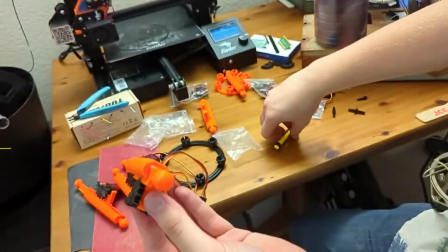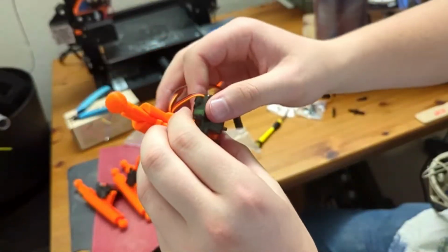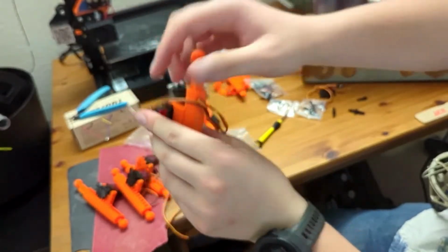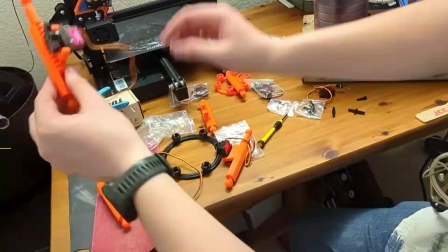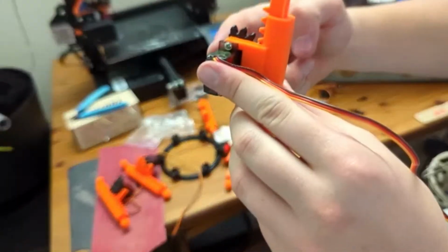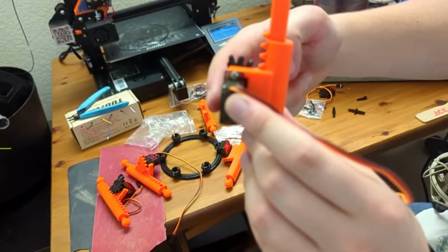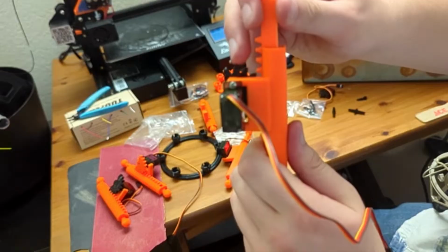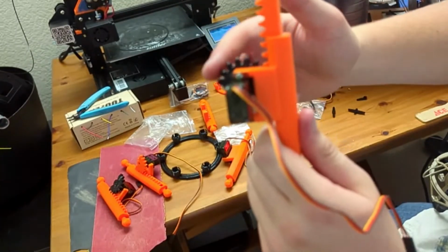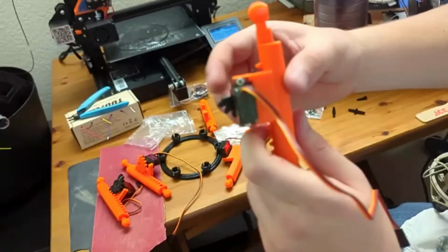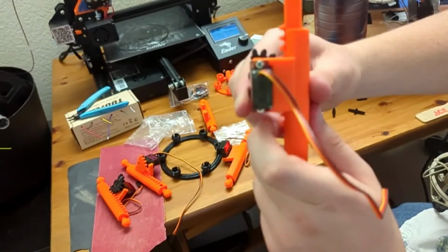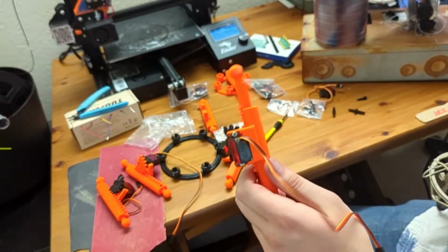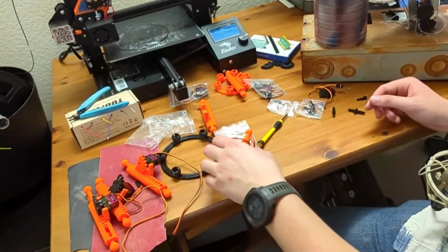So for the most part, it's going to sit right in the middle of its actuation. And at the middle, you can see none of the pinion gear, let me show you one of these, none of the pinion gear is sitting past this servo. So it minimizes the space used by the animatronic in the most common position. And then as it goes up, you can see it sticks out, but that's inevitable. And same with going down, it sticks out past the servo. But where it's going to be most of the time, it's clear, and it leads to minimal invasion of space.